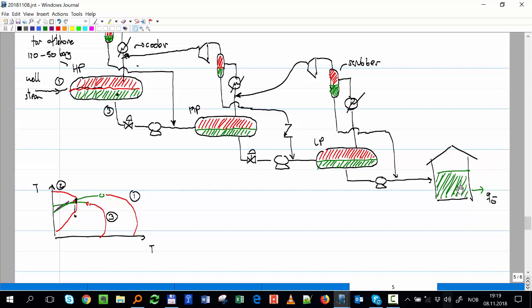But when we have gas, okay, like for example LPG, the pressure is higher. It's not atmospheric. It's higher. Okay, so a sphere is the most efficient shape to keep the thickness of the vessel as small as possible.